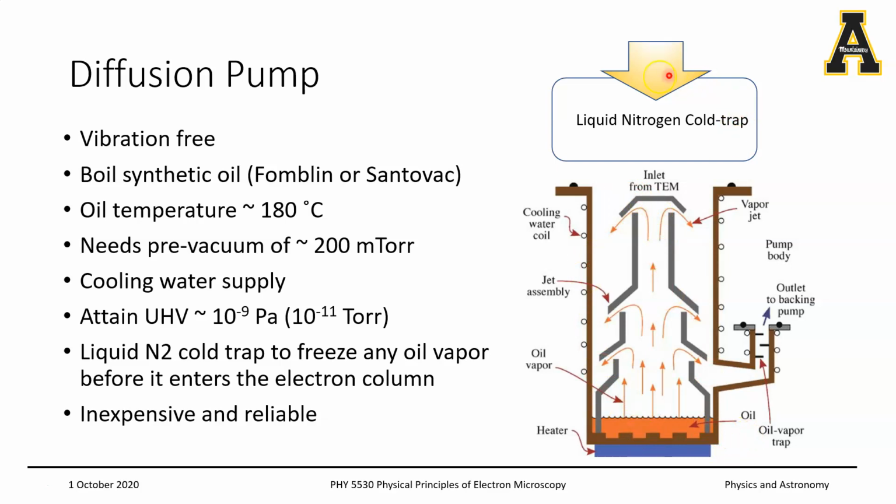And keep in mind that the diffusion pump needs to be connected to the backing pump or your roughing pump, which is maintaining a rough vacuum. So all the gas molecules that were impinged by the oil molecule, and then slid down along the walls of the diffusion pump while it is cooling, are eventually sucked out by your backing pump.